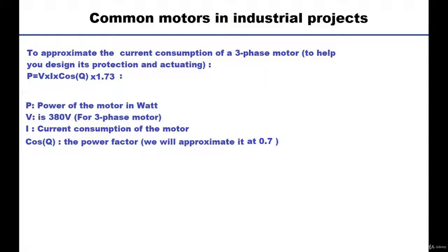And once we connect it to a real load, the power factor is going to be between 0.7, 0.8, 0.9, it depends. The logic behind this is that if the motor is not loaded, it does not need all that power, so it will use only a fraction of it. That's why we'll have a really low power factor. But once the motor is loaded with the machine, the motor is going to consume much more power and the power factor is going to be improved. Usually in our calculations, we use a power factor between 0.6 and 0.7. Here we are going to go with 0.7.